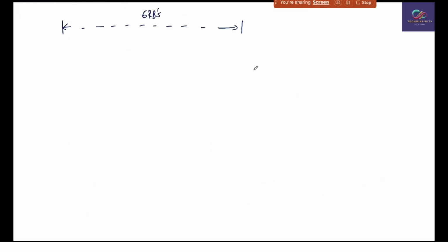So there was one parameter called PRACH frequency offset in 4G. You see that parameter in SIB2. Now the difference between 4G and 5G SIB is that in 4G we get these parameters in SIB2, and in 5G we get them in SIB1. The PRACH frequency offset says one resource block number, let's say 6.